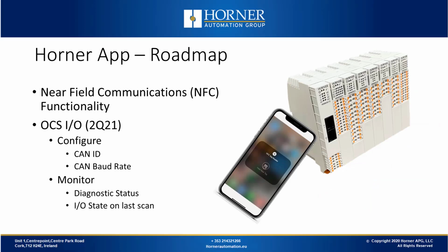We are in the process of designing the next version of the app, which will include NFC functionality. If NFC is enabled, you can configure some details using NFC by holding your phone close to the device. You can use this to set the CAN ID and the CAN baud rate, and monitor the diagnostic status of that particular I/O base. You can also see what the I/O state is of the last scan.